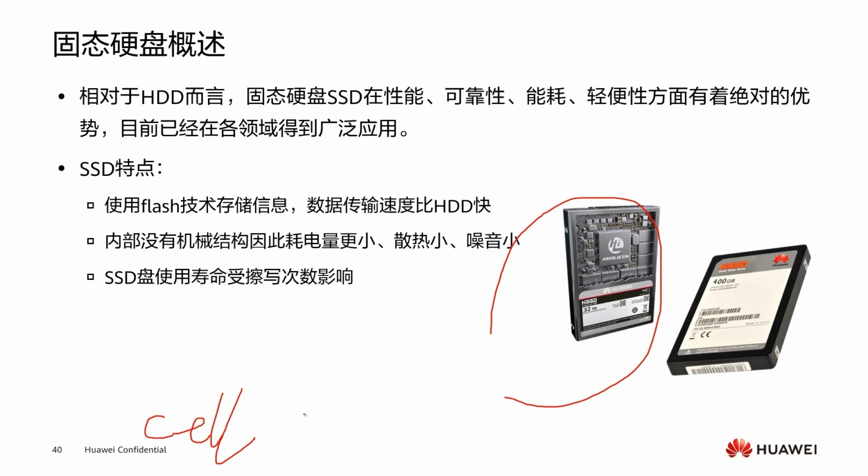But this does not mean that their lifespan is infinite, because NAND flash is a non-volatile medium. The original data must be erased before writing new data, and then the data is written. But the number of erasures of each cell is limited. So when the number of erasures reaches the limit, this cell can no longer continue to read or write data. SSD is mainly composed of a control unit and a storage unit.